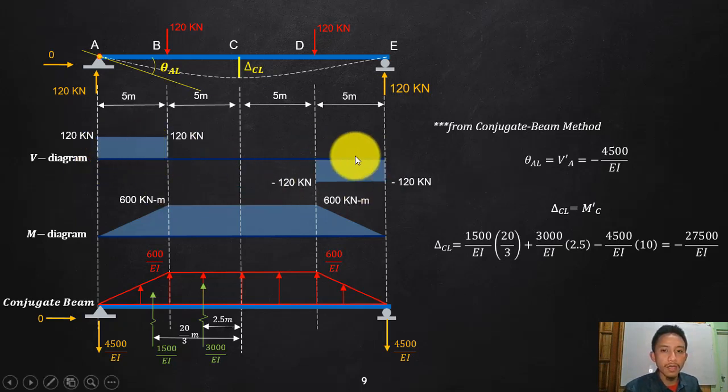Then of course draw my moment diagram. We do not have a moment there, so initially it is 0. By the way, if you recall drawing shear and moment, we should be doing it from left to right. Okay, we are moving left to right. So no moment at A, since that is a pin. Do not mix up with your original indeterminate beam. Let's focus on our new determinate beam. So there is no moment there, so that is 0.